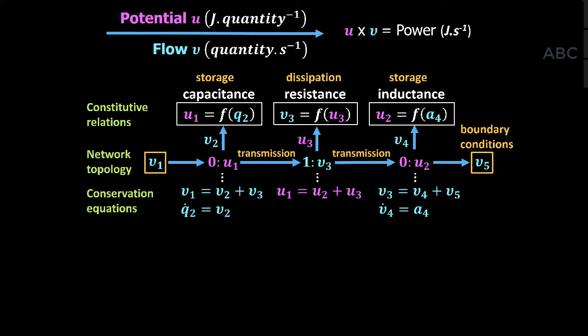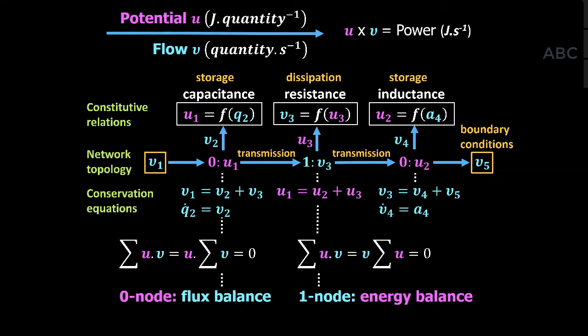Now, here comes the really beautiful aspect of bond graphs. If you think about a zero node, what you're saying is that because we want energy to cross this node without loss, remember our only losses are occurring in a dissipative mechanism, a resistance, a damper or a resistor or a reaction, depending on the physics, this point here has to conserve energy.